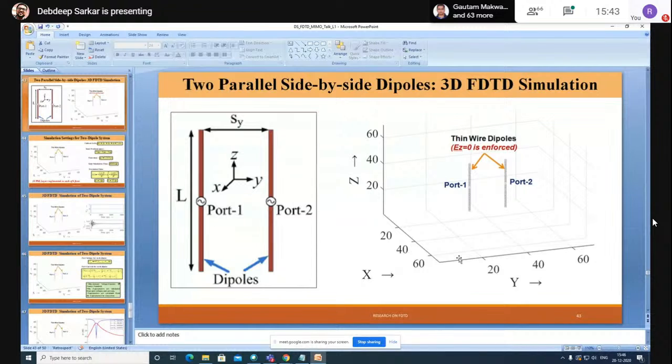If one wants to emulate the quiet zone measurement in an anechoic chamber, that might be possible, but simulating a large chamber in FDTD might not be the best advised method, and people have to look into some other techniques there.